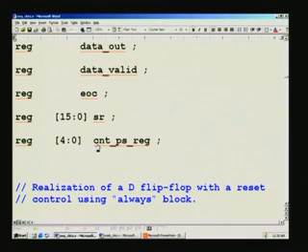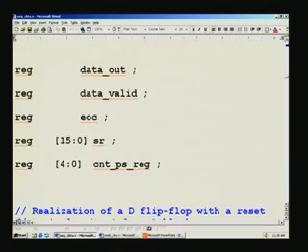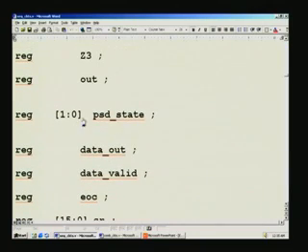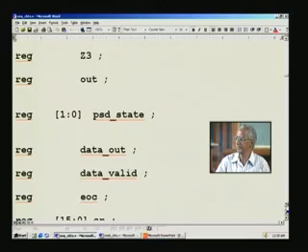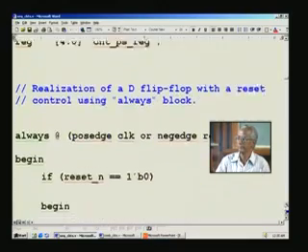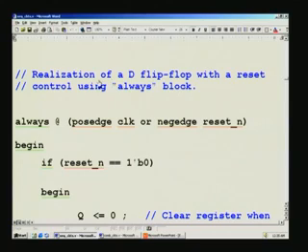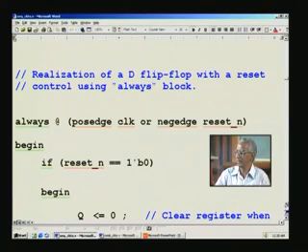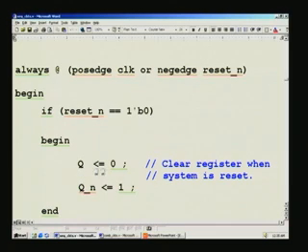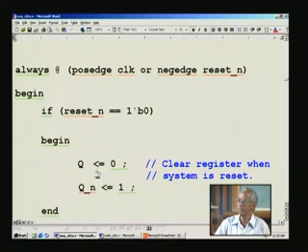So, finally it ends up in, I think this is a pattern, yes, that pattern sequence detector IOs here. Now it starts the code for each of these, and if you see here, it is nothing but a D flip flop which was put on the board, if you remember, and you have an always block, and with positive edge of clock or negative edge of reset only you take the action, and you can reset the flip flops whenever a reset is applied.